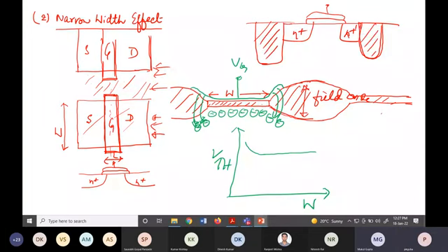So you see, this fringing effect will not be there because it is very thick here. With field oxide, if you go here it is very thick, but where it matters it is very thin, right? As the field oxide is thinner here, the electric lines of force manage to fringe, and they manage to form immobile ions, and that requires extra threshold voltage. I hope it is clear to you. Is that okay?